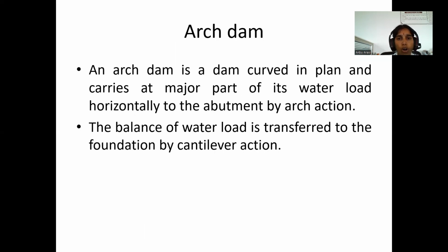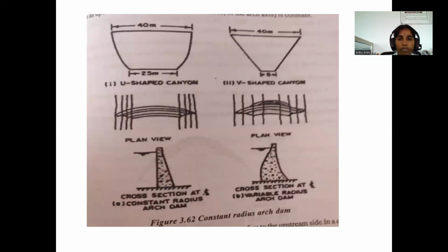Next, arch dam. An arch dam is a dam curved in plan and carries a major part of its water load horizontally to the abutment by arch action. The balance of water load is transferred to the foundation by cantilever action.